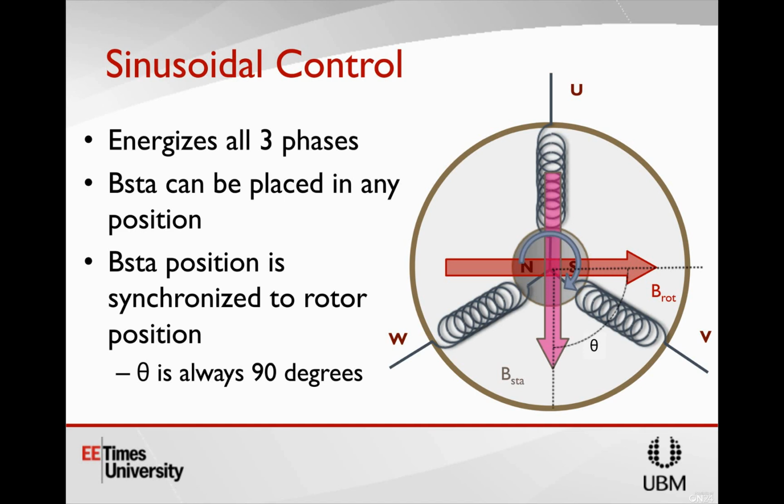So having those Hall effect sensors can be useful in FOC control as kind of a sanity check when you're doing this startup. You just use them to start up and then you can keep running from there. It also helps eliminate some of the robustness issues you run into with Hall effect sensors, in that the application would still work if those Hall effect sensors didn't exist. They'll just work better if they're there.